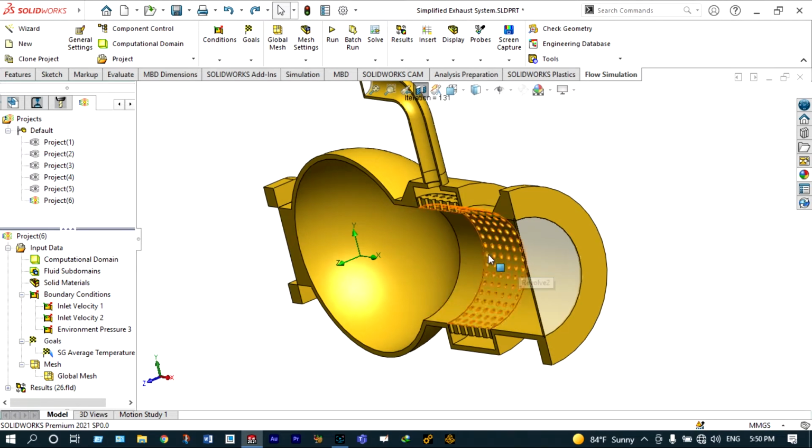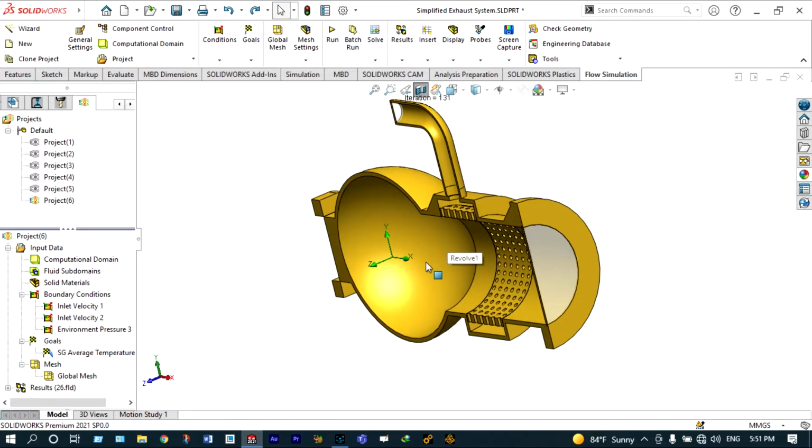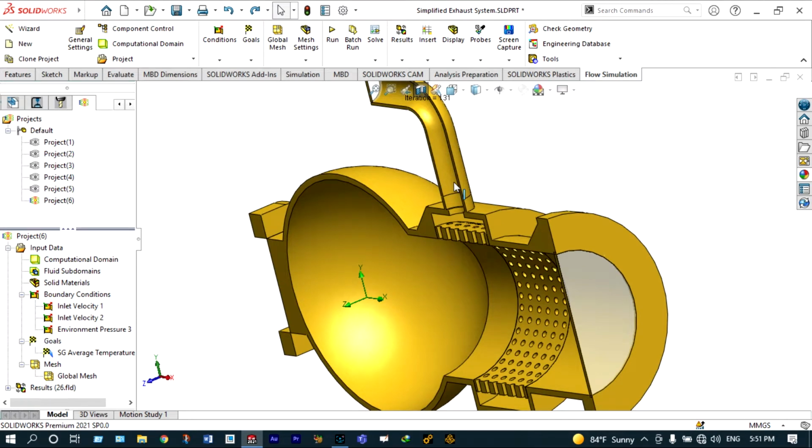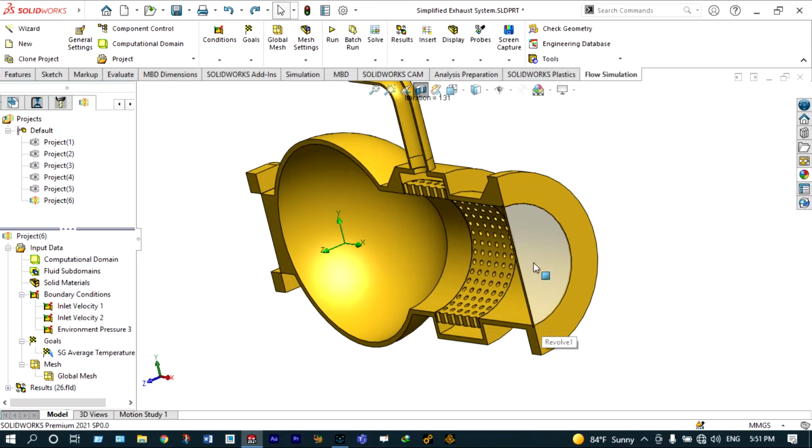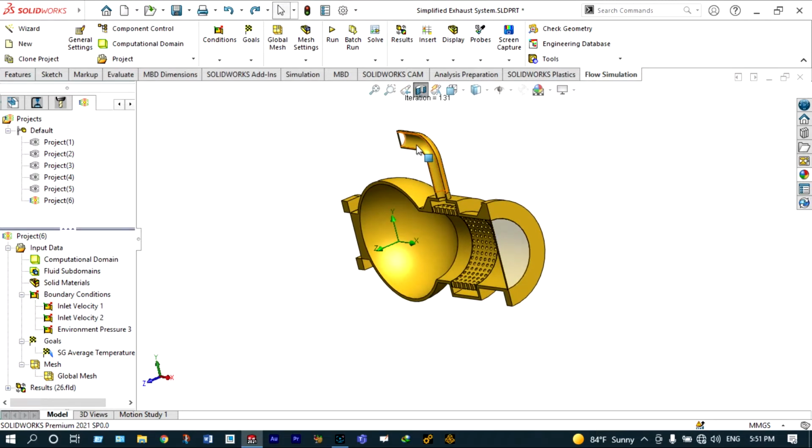At this location homogeneous fluid mixing will occur, and finally at the exit location we get the homogeneous fluid mixture at a reduced temperature. The temperature at the exit location can be controlled very easily by controlling the mass flow rate or the velocity of water at the inlet location. In this case we are considering that the velocity of hot water will be fixed, and to get the reduced temperature at the exit location we can vary the velocity of water at the cold inlet.